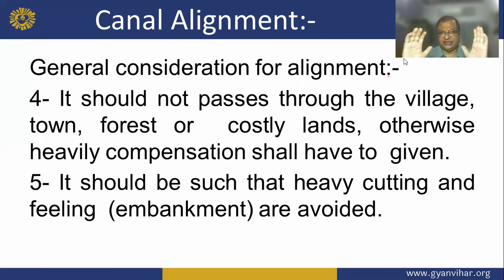Now, general consideration of alignment. It should not pass through a village or town when you are planning a canal. So generally you have knowledge, in any case of emergency, you should not pass through a village, town, forest or closely built land. Otherwise, heavy compensation shall have to be given. It should be such that heavy cutting and filling of embankment are avoided.